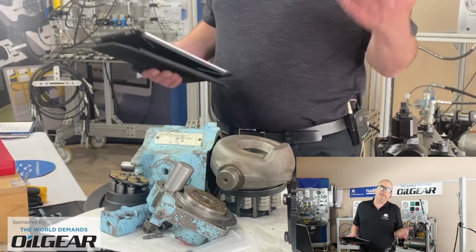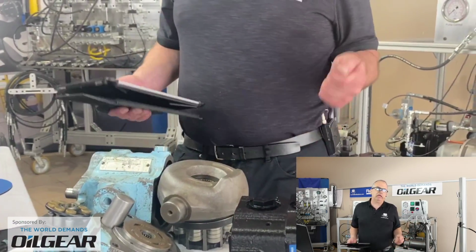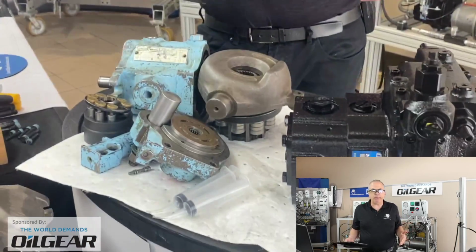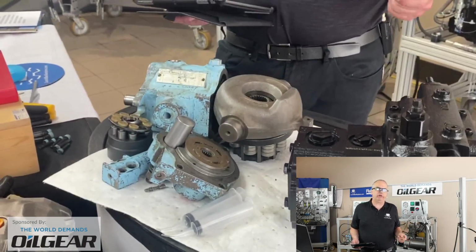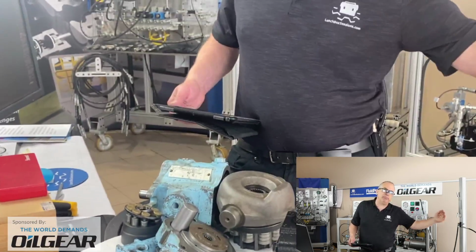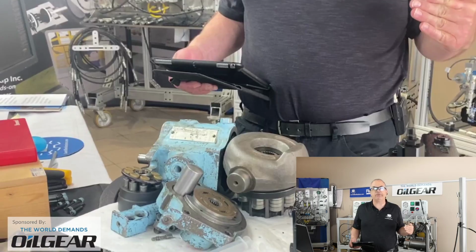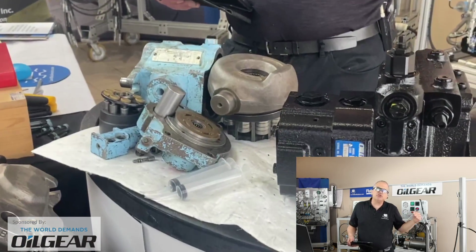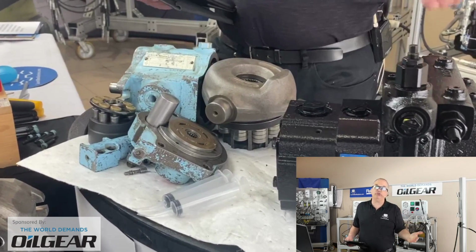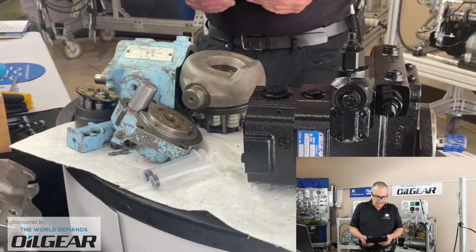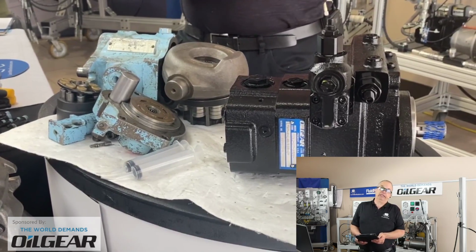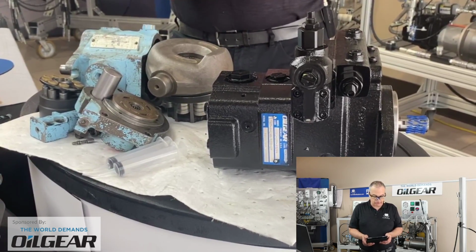But the piston pump gives you the ability to control. It gives you the ability to work with a multiple number of different pressures, depending on what type of controller you've got. There can be torque or horsepower limiting controllers, which can help prevent the engine from stalling if the system's overloaded. There's just so many control options that come with piston pumps. And of course, as we mentioned back near the beginning, energy savings for sure by not pumping over a relief valve any more than absolutely necessary.